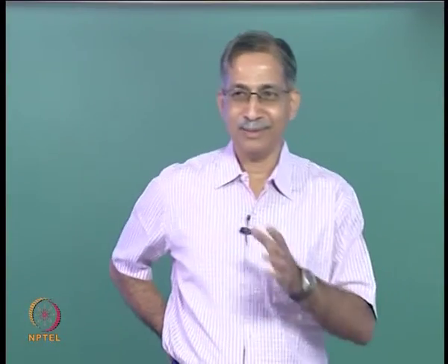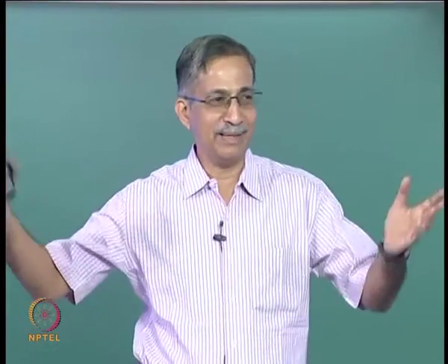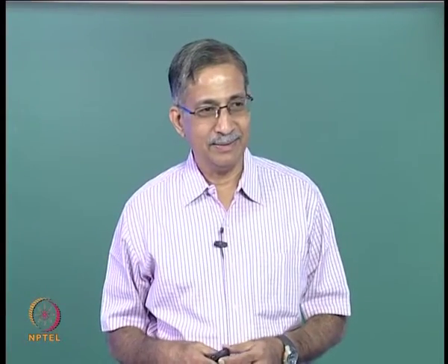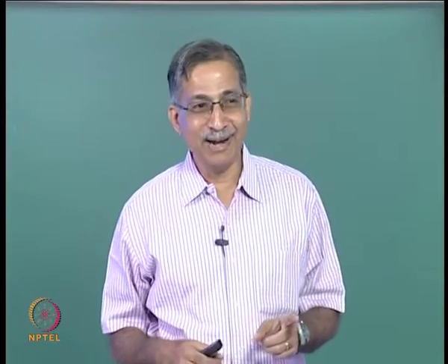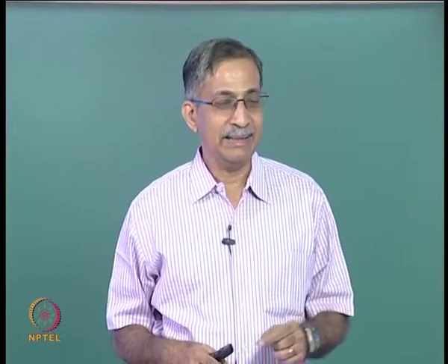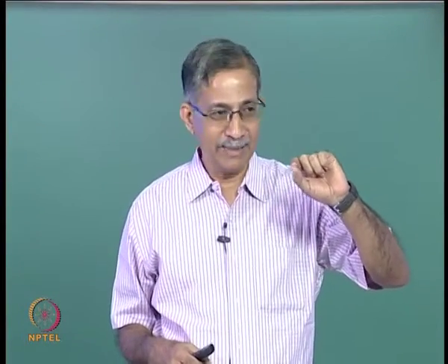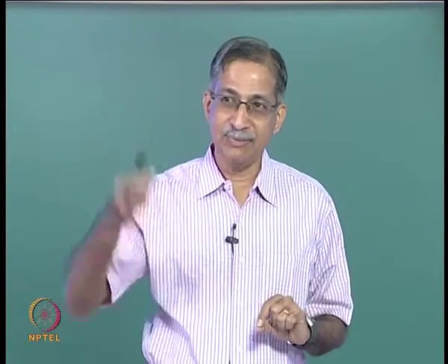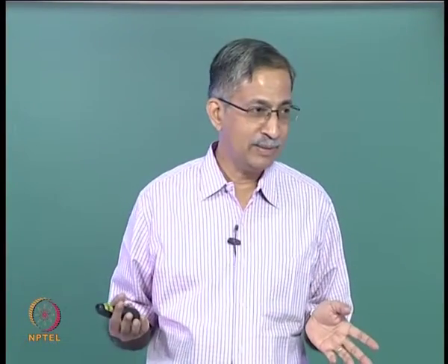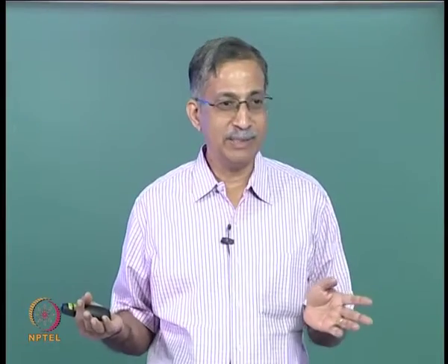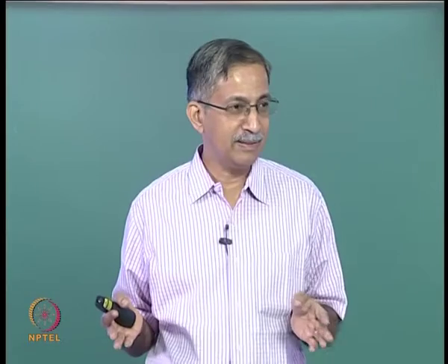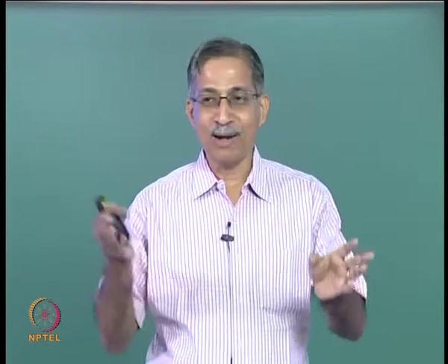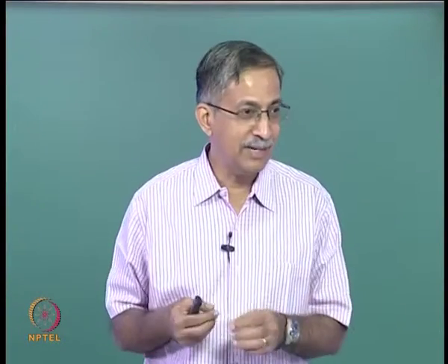Deflection. Compatibility is a big thing. Displacement. Deflection. Energy. If I ask you all to calculate the strain energy in the beam, once you have these forces, you have the bending moments, and once you have the bending moment distribution, you can calculate strain energy, which is an internal energy, internal elastic energy. So you will all have different values of strain energy.